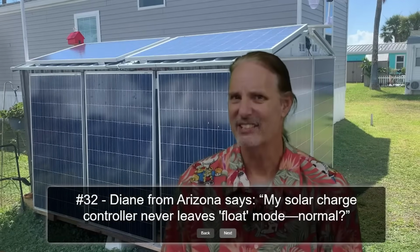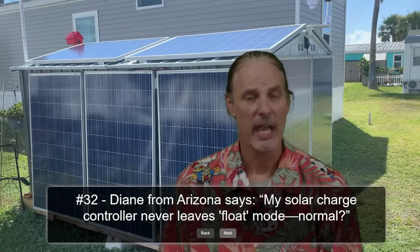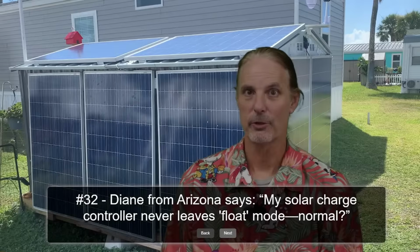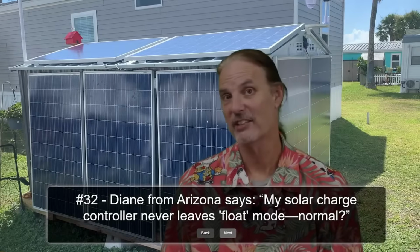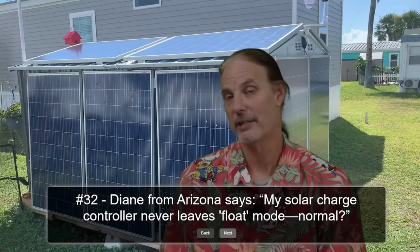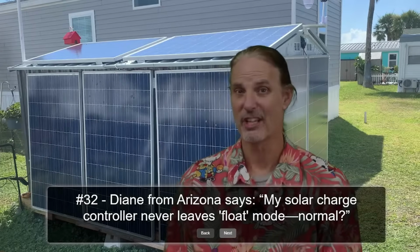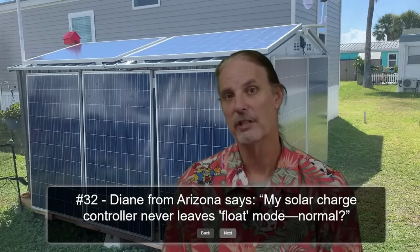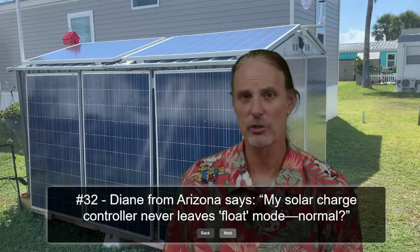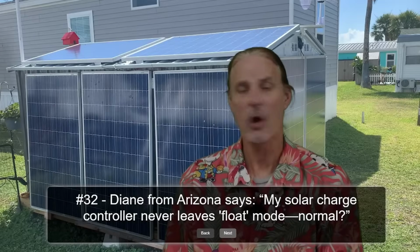So my guess is that you've got the charge voltage set too low, and it immediately drops to the float voltage, which in some cases would not have to be set lower. It could be set exactly the same. So maybe you've got them both set at 54 volts or something like that, and it just never goes into actual bulk mode. I would mess with the configuration. If it's an inverter, check the configuration in the inverter. If it's the charge controller from Victron, you definitely want to get into the configuration settings and look at it there. But no, it is not normal.